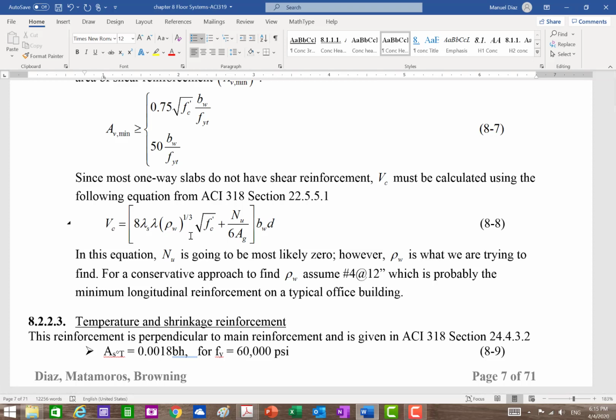All right. And so, remember, we have done this, we have practiced this. I think some of you made mistakes on the homework on this, right? On the quiz too. Because you do not use minimum, you have to use the third formula in the shear, and it has this size factor that will bring it down if your d value is more than 10 inches. Right? And so that's very important. So let's review that.